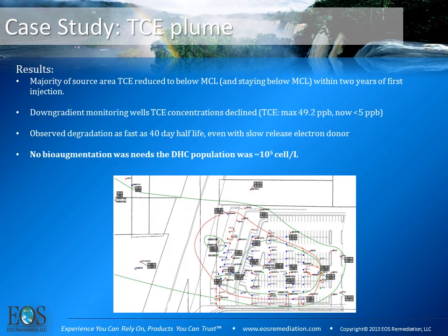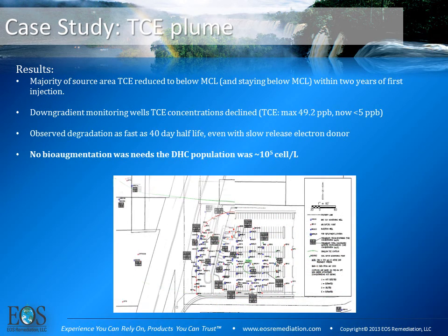The last thing I'll mention is that this engineer did not bioaugment. They did not add any of the Dehalococcoides to this site to promote dechlorination. That's actually something I haven't talked about yet, is bioaugmentation and the introduction of microorganisms into a site. You can see that the plume at this site went away pretty much over the life of the project. It went from that very large plume to essentially this one little green dot here. So a great success. Now let's talk about bioaugmentation.